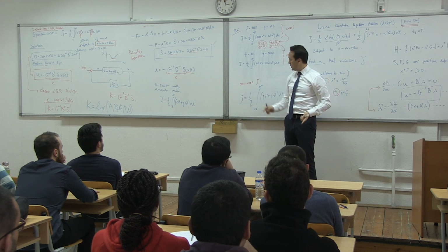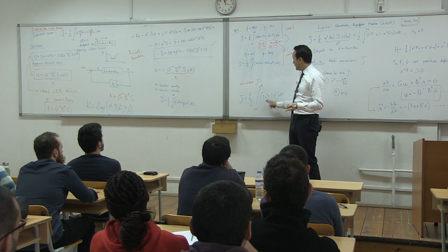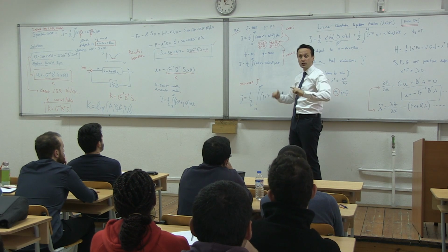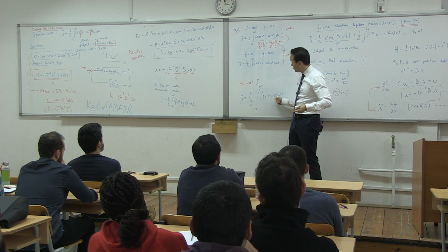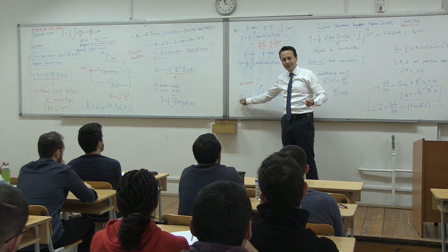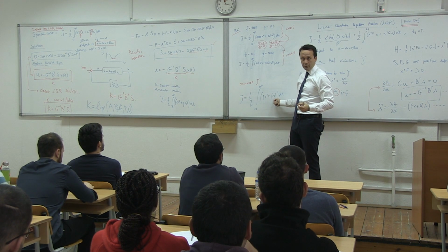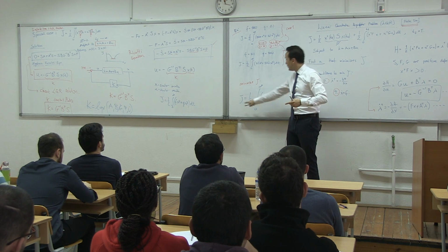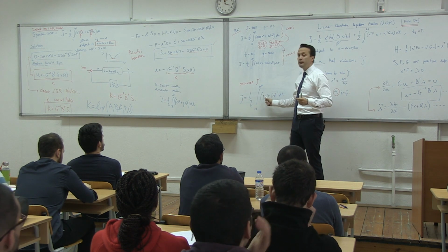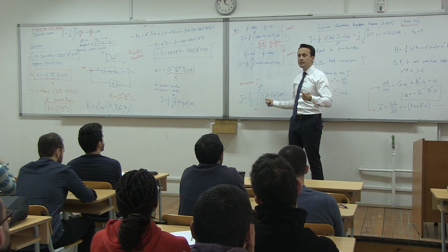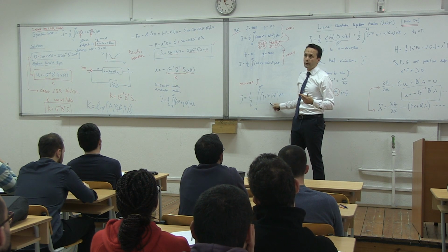And in terms of the optimization problem, it doesn't matter. You can have 1, 1, 10, 10, 1000, 1000, doesn't matter. It will still find the combination of x and u that will minimize j. So although in total the j will be larger if you choose 1000, 1000, the combination that will minimize j will be the same. The combination of x and u will be the same as if you would choose 1, 1.